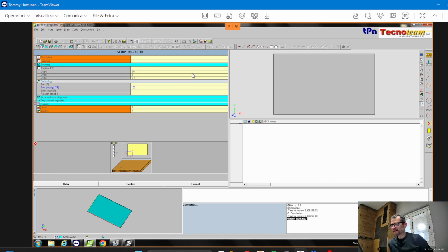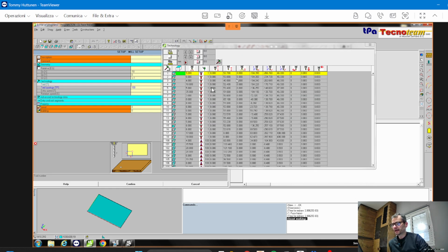And the tool number is the tool number that you have on the router. Maybe I don't remember it. About the tool in the machine, we have a complete lesson where we speak about the tool configuration and how to call a tool and why the tool is called in this way or not. But if you don't remember, don't worry, because I have the possibility to click on this little square. And here I have all the configuration of the tools in the machine. In this page you have all the tools, the tools for the router and the tools for the boring head.